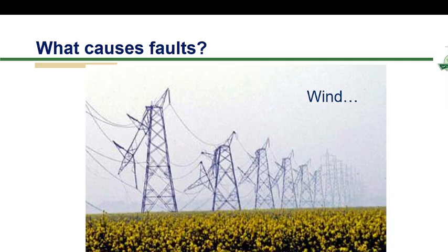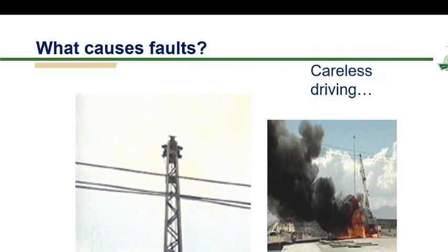All right. This slide highlights another critical cause of faults in the power system: physical damage and environmental impact on infrastructure. As you can see in this figure, external factors such as mechanical stress, weather conditions, or accidental contact can damage cables and insulation layers. Sometimes wear and tear combined with environmental impact may lead to insulation degradation, cracks, or breaks in conductors. These defects can result in short circuits, ground faults, or even complex system failures. Therefore, regular inspection, preventive maintenance, and the use of robust materials are essential to ensure system reliability and to minimize unexpected outages.